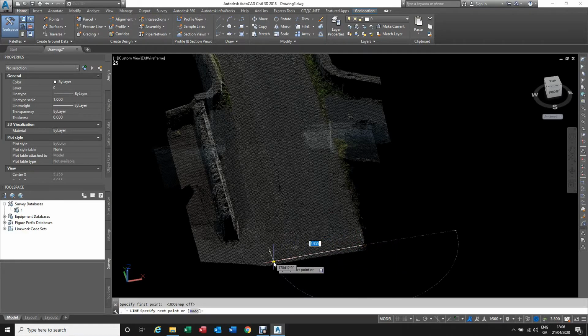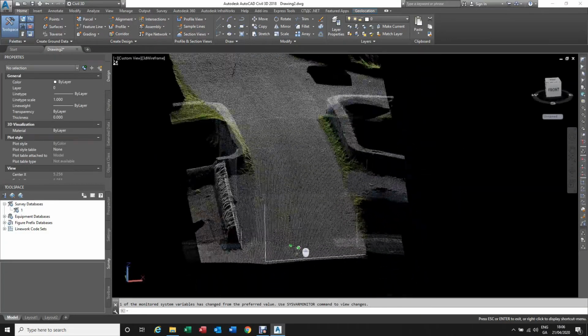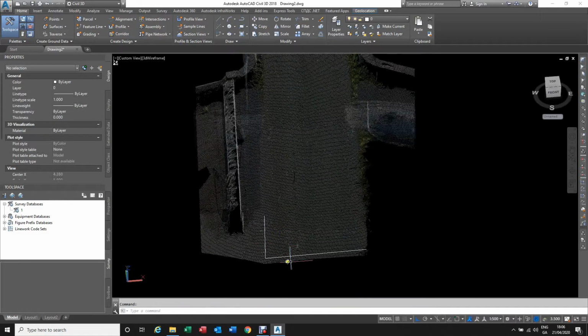You can toggle with F4, switching on and off. So you need to set something like that to have an XY plane where you can see this from top view, because I will show you later why. It's just make a UCS. I switch off this one, ortho, and just want F3, the snap on for this. And yeah, I got my plane now.